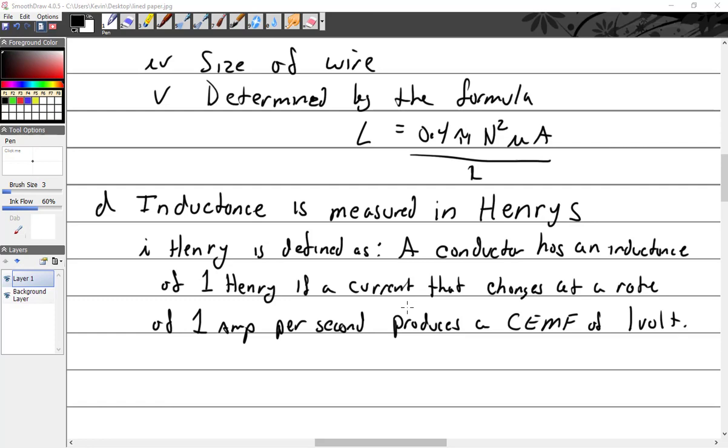So in a DC circuit with an inductor, it's going to have inductance. Current no longer snaps up and snaps off instantaneously. When the switch is closed, current begins to flow, but is then opposed by EMF in the coil that you've created. So it actually takes a little bit of time for it to build up. You just don't notice it because the time is very quick. The greater the inductance, the longer it takes. And the same effect when I shut down the circuit, it's going to oppose it. It's going to say, whoa, don't go anywhere.